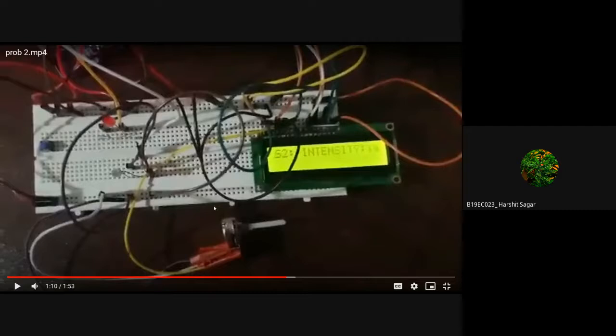Actually, you have this photoresistor, so you have to connect one potentiometer or resistor so that you can get the variation, right? Oh, okay. But sir, there is a very small variation, 16 to 6. Right now, for the photoresistor that you are using, you might be doing a voltage divider circuit here, right? Yes, sir. What is the resistance that you are using for that?